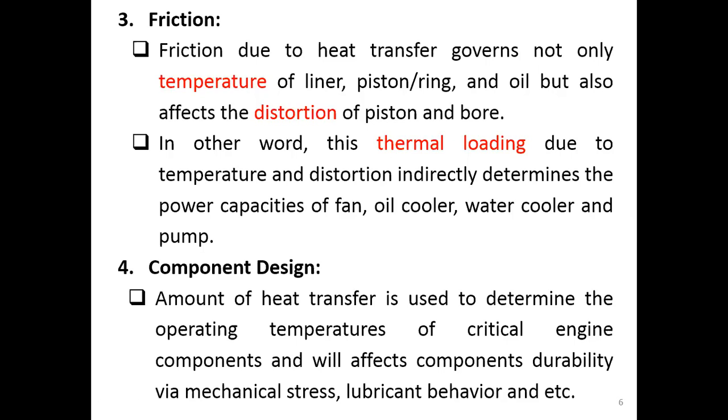This heat also affects your component durability via the mechanical strength, via the lubricant behavior, and others. So you have to know the amount of heat transfer that will happen and include that in your considerations when you design the engine component, because the lifetime of the component is going to be affected by this amount of heat transfer.